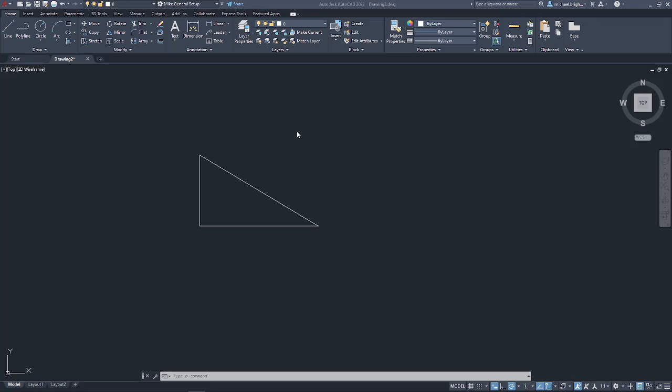Okay, so we've done the lines. That's how you draw your lines. One of the most basic things you need to learn about CAD just before we go any further is your two windows. You have a blue window and a green window. Your blue window is you pick up a point and drag to the right, it'll create a blue window. You drag to the left, it'll create a green window. And these two windows, very important.